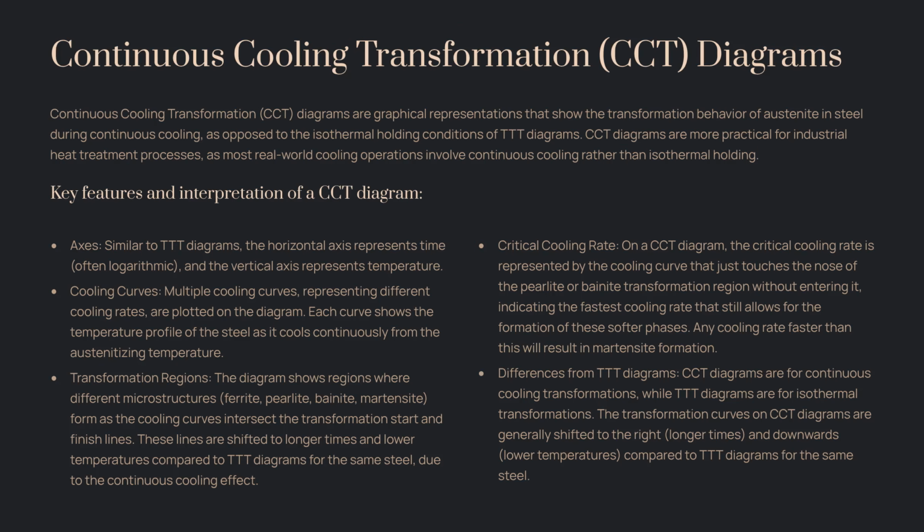Method: plotting cooling rate curves on a TTT diagram. Concept: critical cooling rate to achieve martensite. Limitation: provides an approximation. CCT diagrams are more accurate for continuous cooling. Continuous cooling transformation, CCT diagrams.